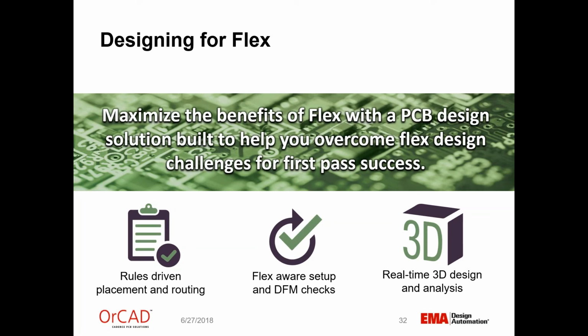Yep, you can use IPC 2581. Not sure if people are familiar with that yet, but more and more manufacturers, especially ones that are doing rigid flex and flex, are accepting IPC 2581 information. It's going to replace Gerber and ODB++.